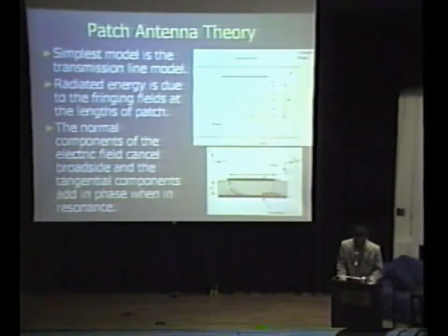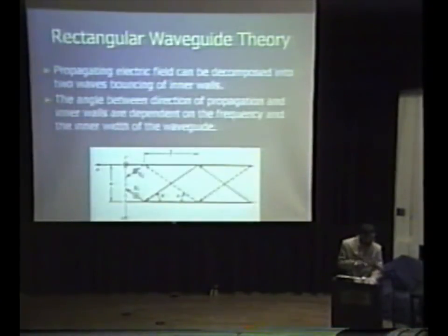These will excite electromagnetic waves broadside to the antenna patch. The next thing is the waveguide theory. Waveguides are used as transmission lines, and you'll get electromagnetic energy propagating down the length of the waveguide.